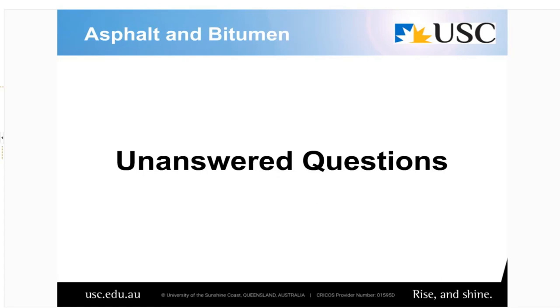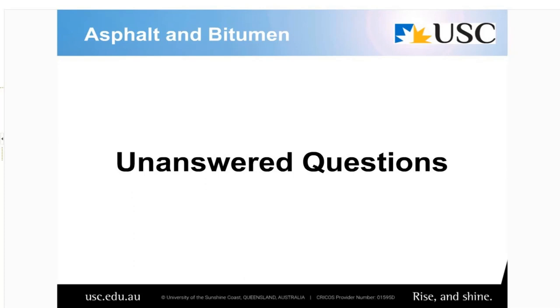So typically 5.6, 5.7 could be anywhere, to be honest, from 5.2 to 6.1, depending on a lot of things, primarily the aggregate that you're using. And that wouldn't change whether you're putting in C320, a proprietary PMB, an elastomeric PMB, multi-grade, it makes no difference which binder you use. That 5.6, 5.7 bitumen content is pretty much the same all the time.